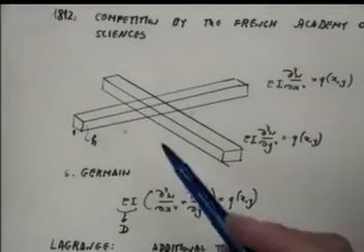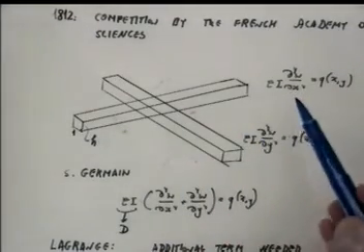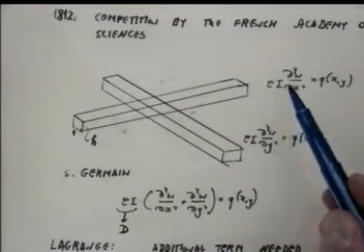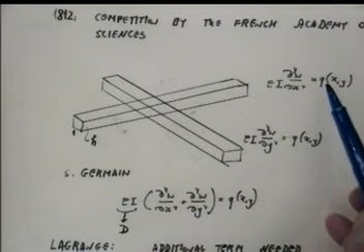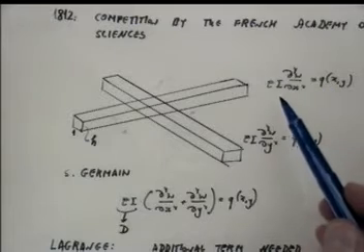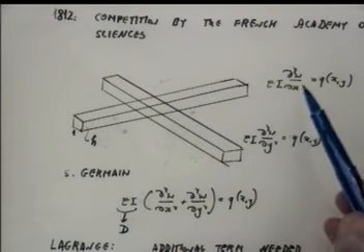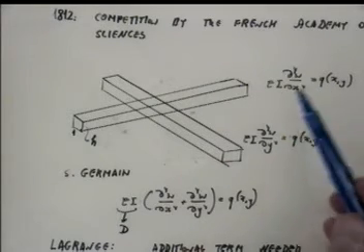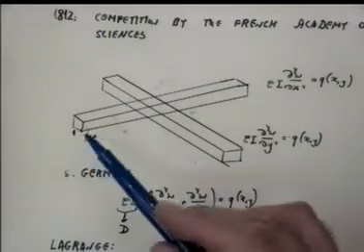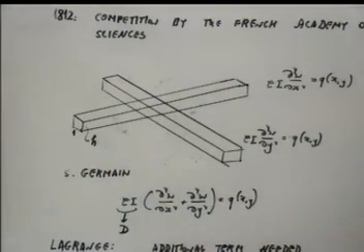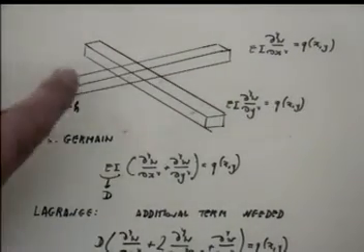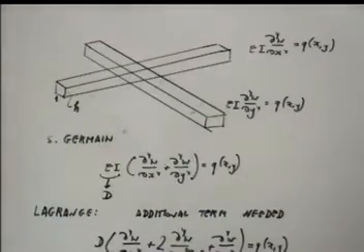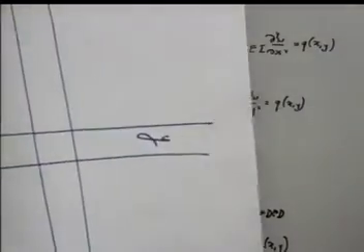So, in the x direction, she says, I should have an equation like EI d4w/dx4 equals q. That is a load. That is a fourth-order differential equation for the beam in the x direction. Now, in the y direction, as we said, that is also a beam.